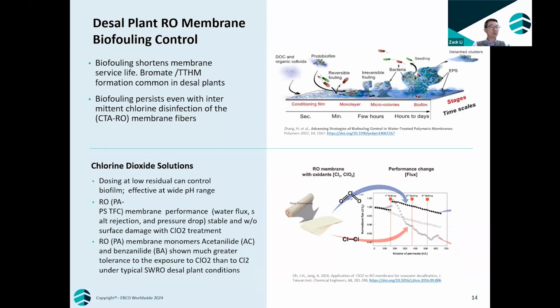seawater desalination plants. Biofouling poses the biggest challenge in membrane fouling control. Biofilms are sticky and thick. They can create very high flow resistance. So biofilm formation usually causes irreversible damage to the membrane surface and forces more frequent than usual chemical clean-in-place operations to sanitize the membrane surface from the biofilm accumulation.